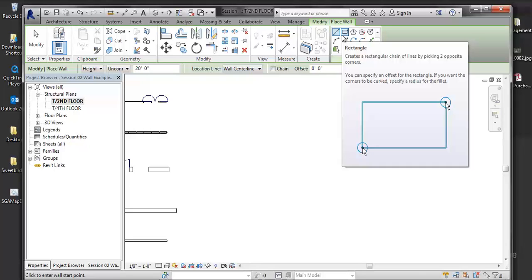When you're picking lines, we'll touch on that later, but to answer the question briefly now, it's really dependent upon what you're trying to do. If I'm on an exterior, and depending on what lines I used, if I'm on a CAD plan and building off of them, if my CAD plan goes all the way out, and I've drawn it where I'm building walls out to the slab edge, then I would be doing finish face exterior, or vice versa, finish face interior.